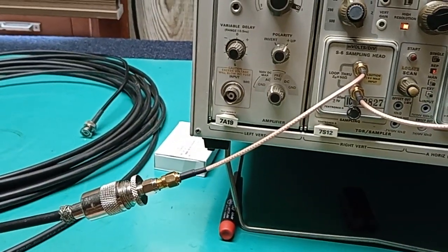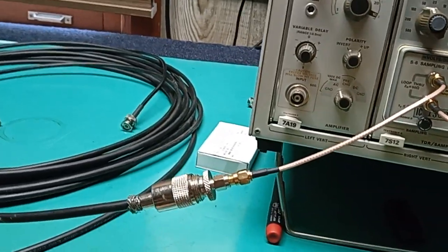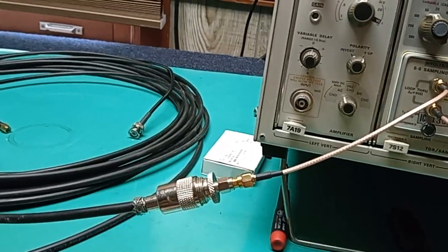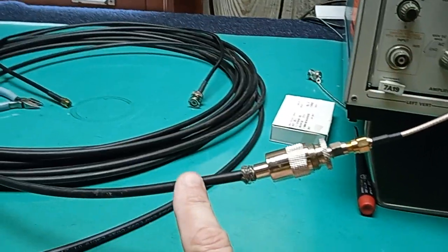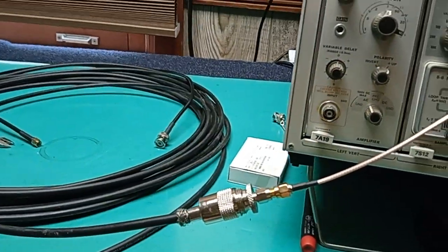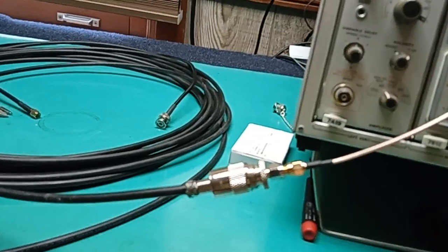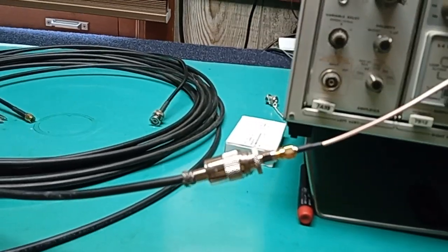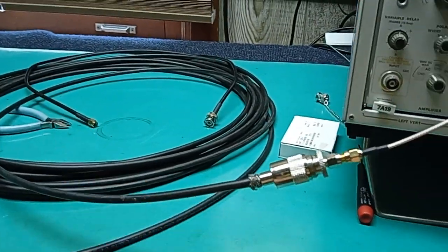Impedance is a series characteristic of a circuit which impedes the flow of current, and transmission lines do not impede the flow of current. At the worst, the dielectric losses constitute an admittance. 1 over Z equals Y. That is a loss. That's also in the time domain because a loss is with regard to propagation time. The further it propagates, the more loss there is.